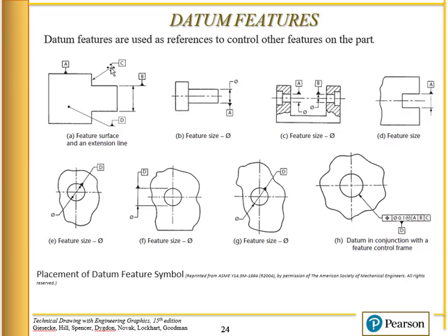C, this datum here, is applied with a leader. And then B here is applied to this surface by virtue of this extension line. So you can apply datums to a surface, to an extension line, or with a leader. In this case, the feature of size, which is this diameter, becomes datum A. Here we're showing datum D with this little reverse triangle is the hole. Here's another way to say that the hole is datum D. And then here's yet another way to do that.